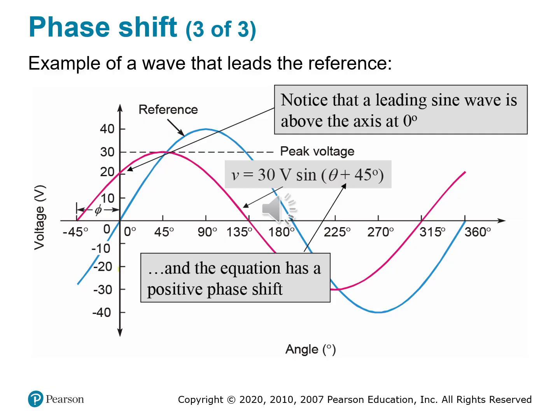So this type of phase shift is typically in capacitive circuits where voltage lags current, and the waveform associated with the current is said to be leading. You'll often hear this phrasing in power systems. So current leads voltage in a capacitor, voltage leads current in an inductor. Again, phase shift gives us a language to describe timing differences, which are critical when analyzing power flow, signal synchronization, or wave interaction in reactive components. And we'll talk about reactive components a little later in this course.